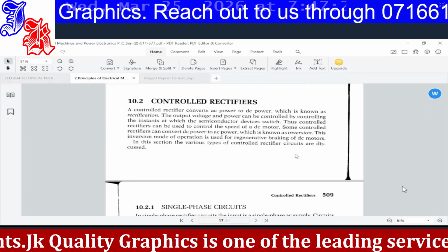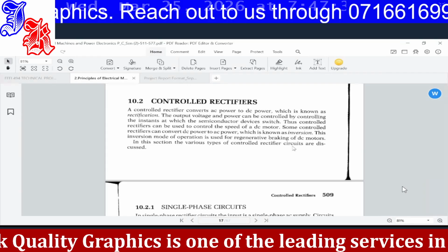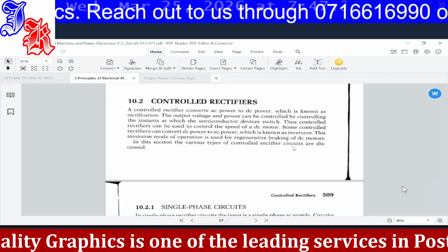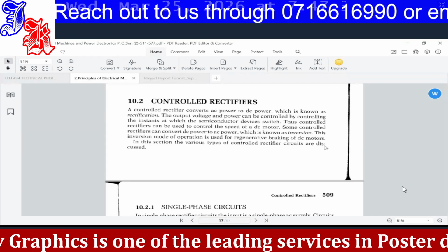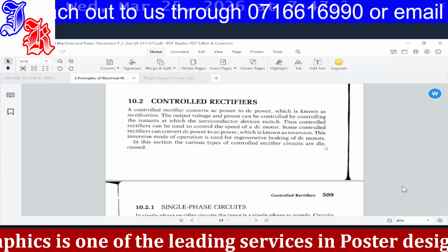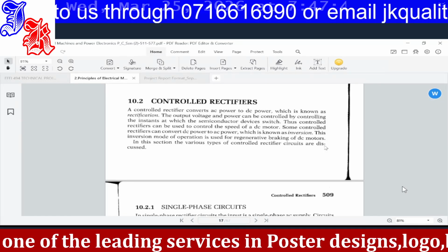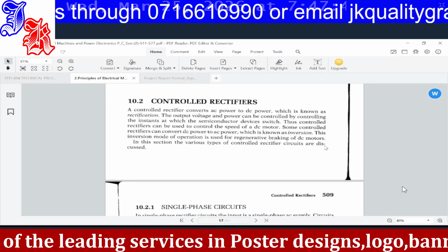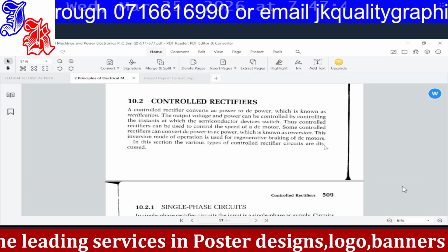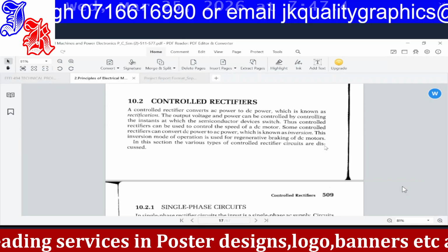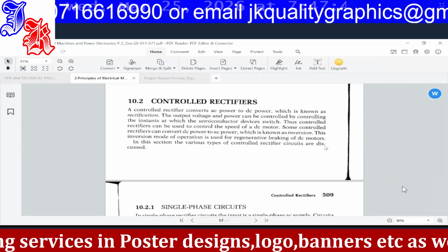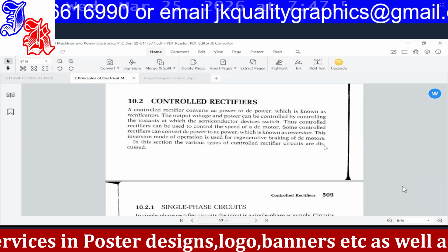Okay, thank you. So if you are done with GTO, we look at the rectifiers. When you say controlled rectifiers, for instance when you are talking about thyristors, we are able to control at what point we want to ignite it, because we have the ability to inject the gate current.